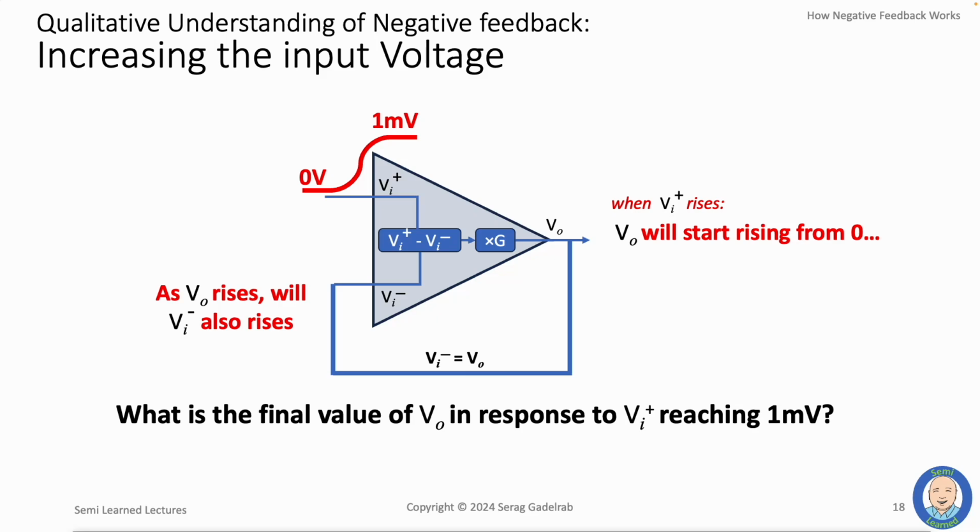The first one is the feedback equation. That is that the voltage on the negative input is really equal to the output voltage. The second equation is the one that describes the input-output relationship of the op-amp. But this op-amp equation is problematic because we do not know what region the op-amp is operating in. Will it be in the linear region or the saturation region? In order to figure out the region in which the op-amp works, let's do a thought experiment.